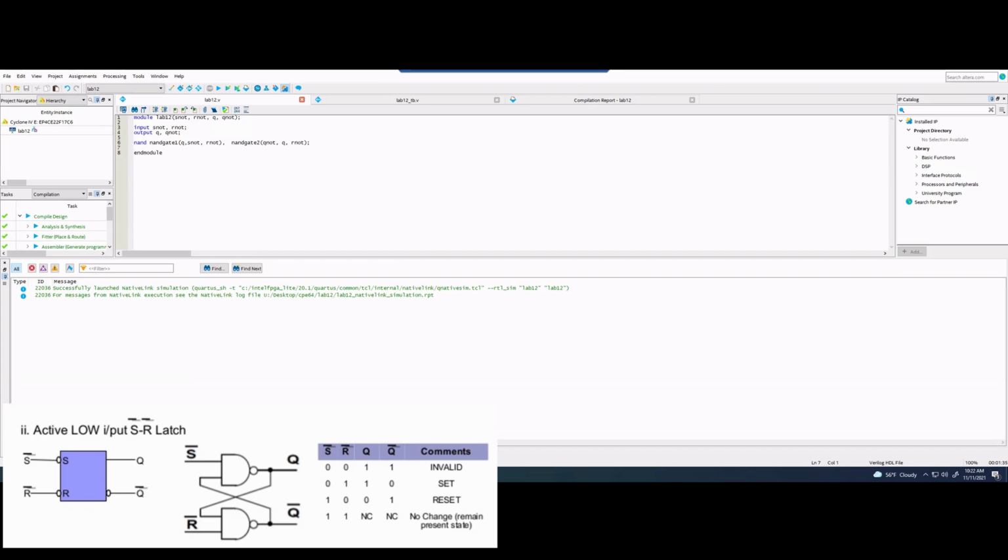We found the error because we have NAND gate 1, and then inside of here we have S0 and then R0. Well, if we look at the actual circuit diagram we're given Q, we're given S0, and then instead of R0, the bottom input is Q0. So we're going to have to change that from R0 to Q0. And let's double check our NAND gate 2 on the bottom. Our output is Q0, yeah. Our top input is Q, and then our bottom input is R0. So we fixed this. Our code is now 100% correct.